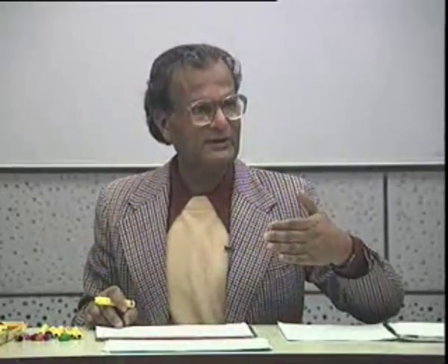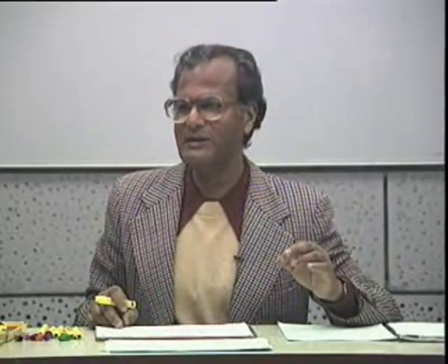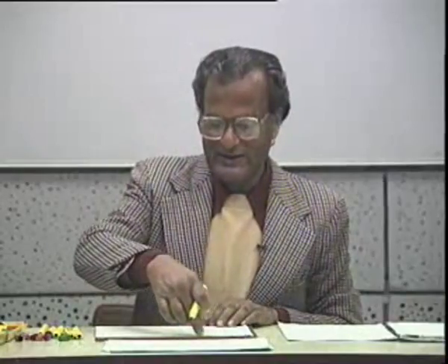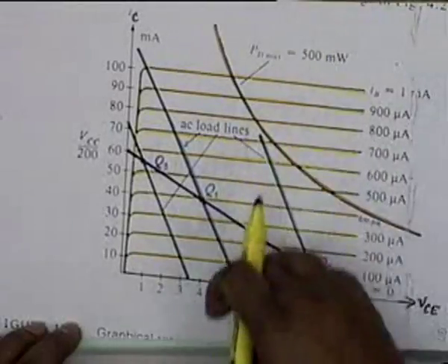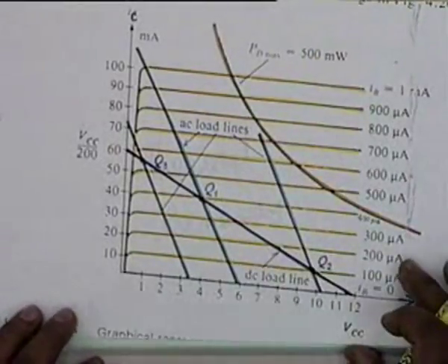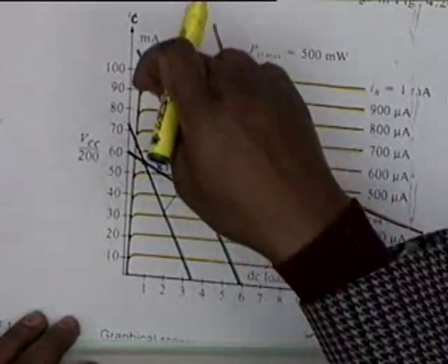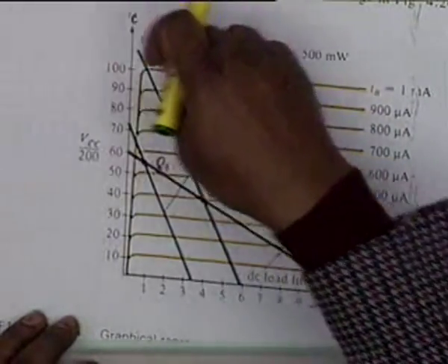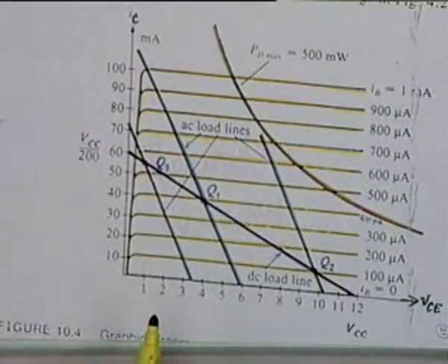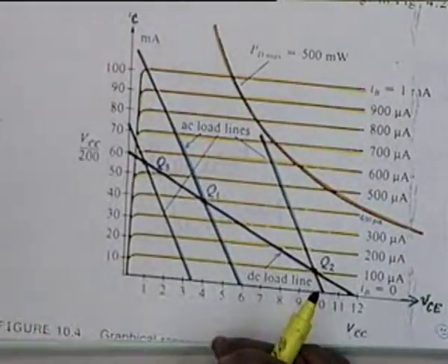Similarly, the current that can be drawn from a transistor, there is an absolute limit. You cannot draw more than that. So there would be a horizontal line somewhere here. For this transistor, this is 800 milliamps. And our operation normally will be restricted to about 1/10 or 1/8 of this, about 100 milliamps. We will not draw more than that.